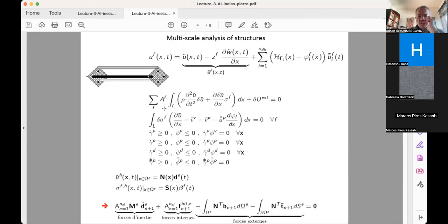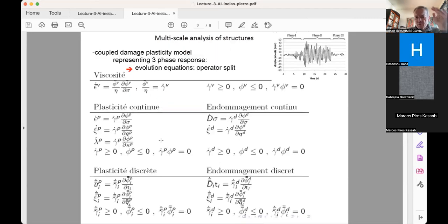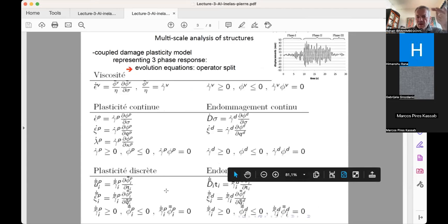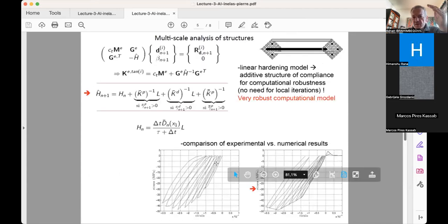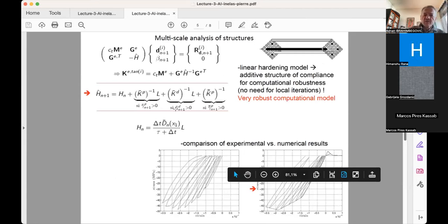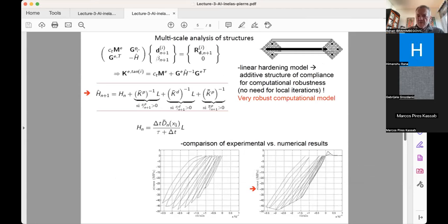So you can go very easily and carry out the computation of all these terms. You get the corresponding influence of the internal variables, and basically you get the corresponding response, whether you are hardening or softening, and so on and so forth. You sum it up into this H, and from this you get the inversion. This becomes H minus 1 G times G transpose, and you get your stiffness matrix. So that becomes very easy. This is just a linear computation.